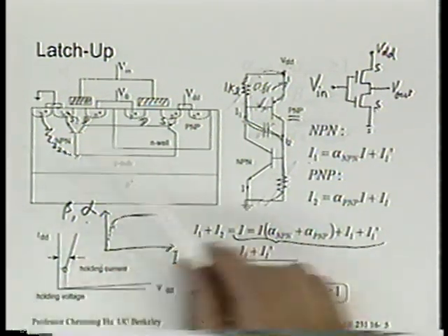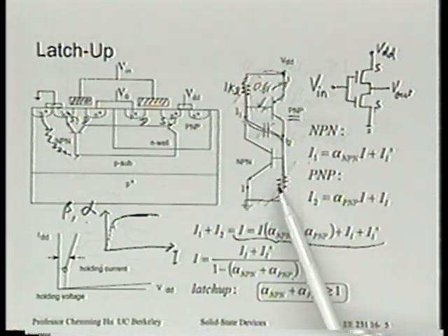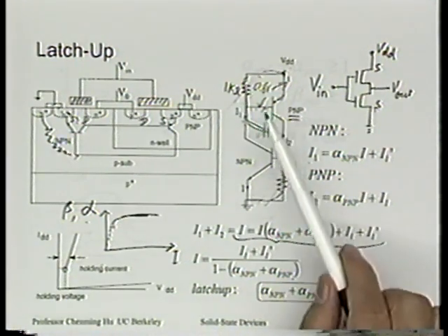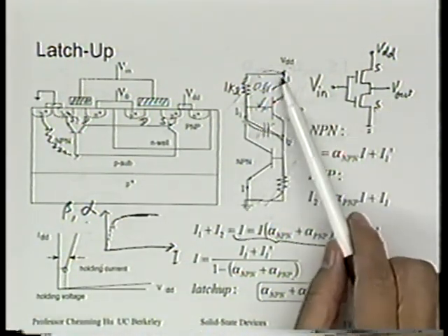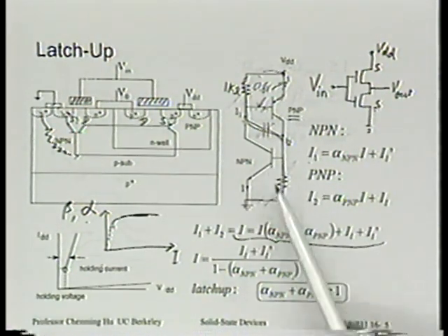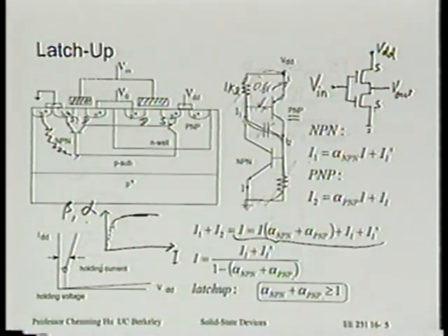Okay. In principle, if you can short out either one of these two emitter-base junctions, you would have succeeded. In practice, we cannot short out either one perfectly, so we try to short out both. Okay? That's what we do. And if you ever find a design with a floating well, that's a no-no. It's a guarantee of trouble. So a design rule checker will always look for any well that's floating. Right? You have to connect the well to VDD or to VSS. Is that right? Okay, that's called latch up.